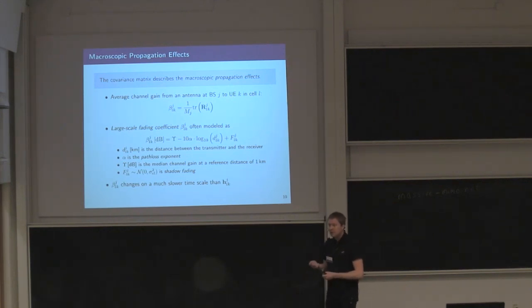First of all, I think in the millimeter wave, the line of sight is the most important case, where you would have a line of sight component in addition to this. Now I've assumed zero mean, but then it would have a mean value. But suppose that you have one large reflection. It goes from transmitter to receiver, bouncing off that wall. That's the only way of reaching me because everything else is blocked. Well, then this covariance matrix here would have a rank of 1 that describes that particular path. And then how much you lose on that path will be the corresponding eigenvalue that describes that.